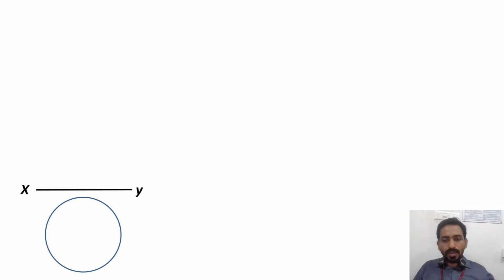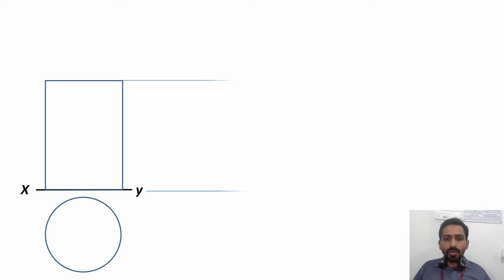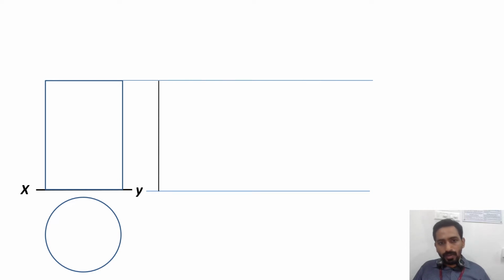So first we will draw the XY line. Now you will draw the characteristic view, which is the simple position, within the top view here, which has the shape of a circle, and now you will draw the corresponding front view. Now the simple position is over, from which you have parallel lines like this. Now you will draw the starting edge of this particular development. So you should get a rectangle. The first edge I have drawn here.